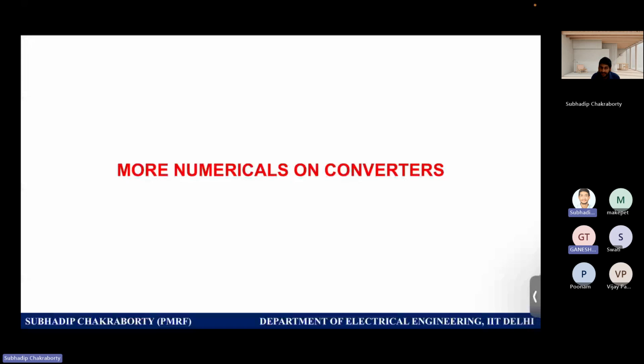That will give you the clue or hint to write the equation, and from that you can derive the maximum voltage that it has to inject. By voltage and current information, you can just multiply and get the volt ampere rating. Either it be series or shunt, some series problems are also given in the assignments, you must have seen, so those solutions are also there.